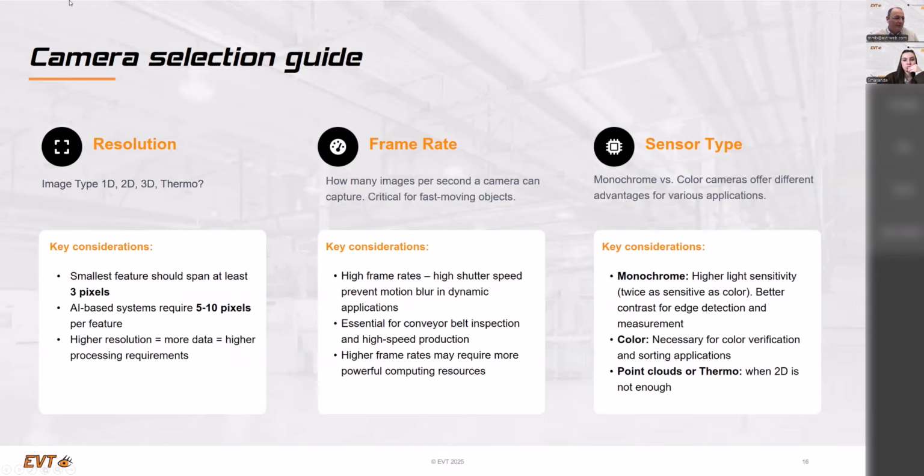And of course, if you need a color or gray image, it depends on what you want to see. If you have to see a color image, a color camera is good. But if you only have to decide between two or three colors, sometimes you can do it with a gray camera and a filter, which reduces the amount of pixels you have to transfer, and of course the speed of the CPU which operates on it.